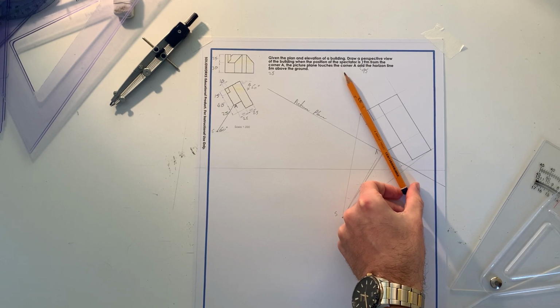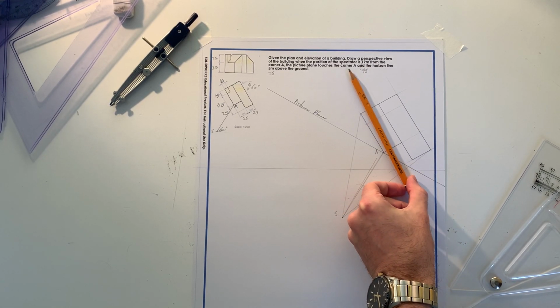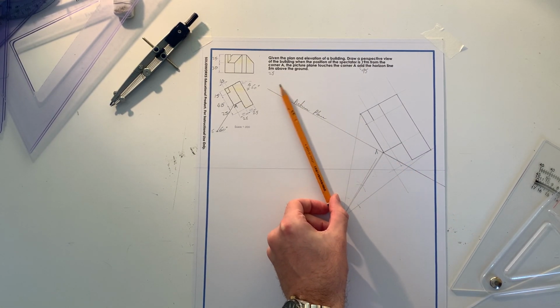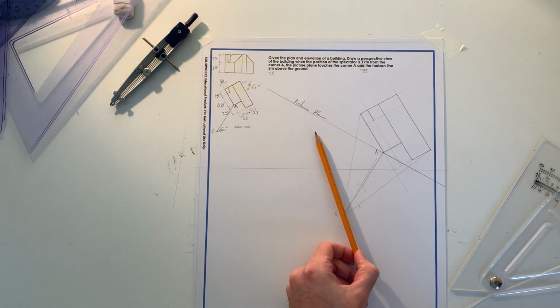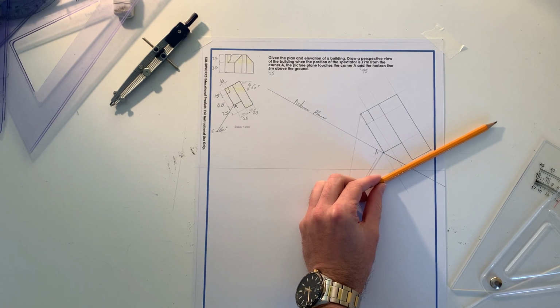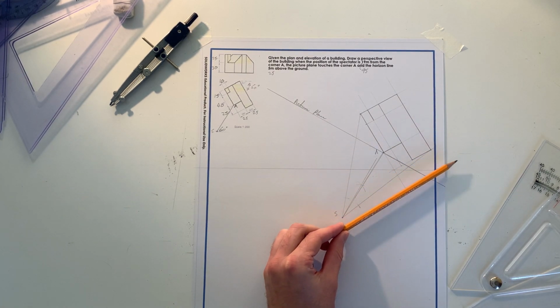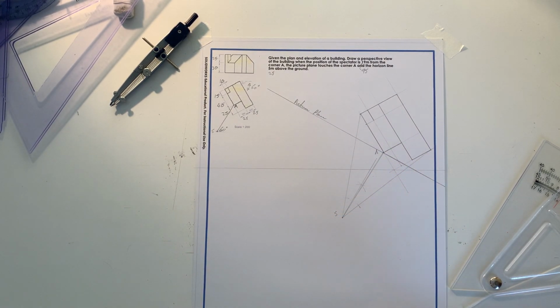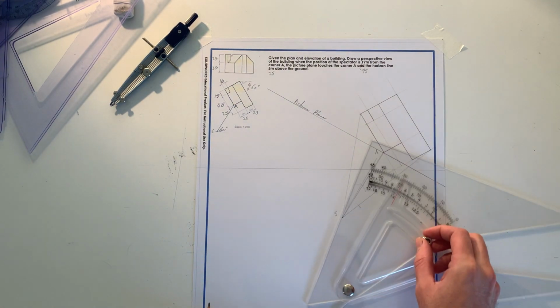To get our VP1 or VP2, so our vanishing points, we're going to have to use a line that's going to be parallel to the sides of our drawing. So a line parallel to the side here, and from the spectator out where it intersects the picture plane is going to be the point. Same thing for our VP2, parallel with the side of our plan from our spectator like so, and we'll get our vanishing point above there.